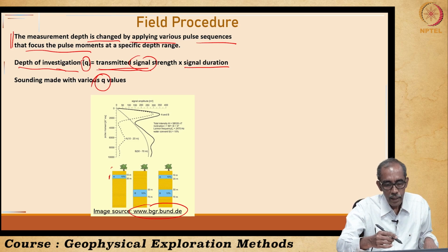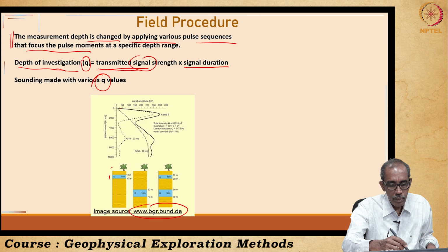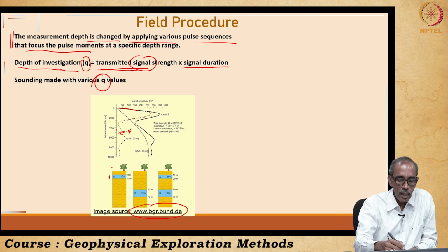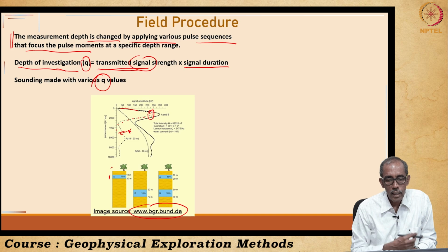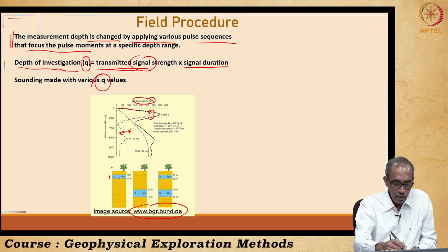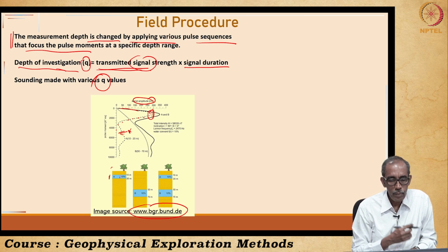The same A layer is sensed by the NMR, this dotted line, right. So, this is A. Here this layer is at a depth of only 10 meters. Here you can see we get maximum signal, the dotted line. So, signal amplitude was very high. What does it indicate? Because within 10 meters you have a porous formation, the blues are water bearing formations, due to which you get very high signal.